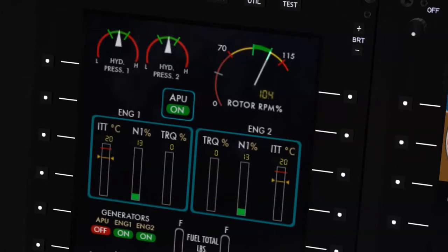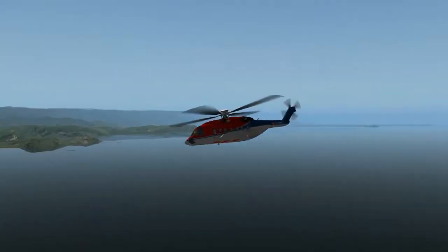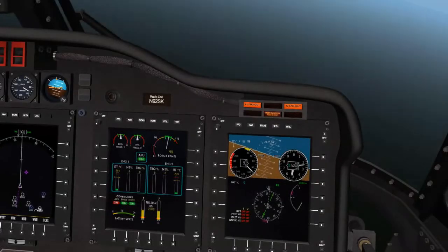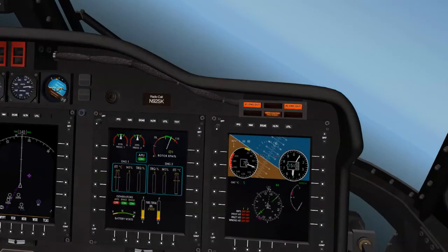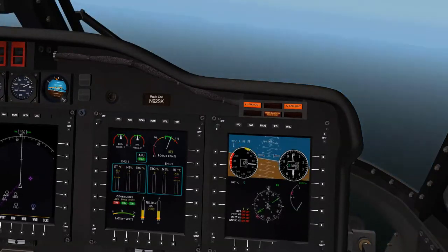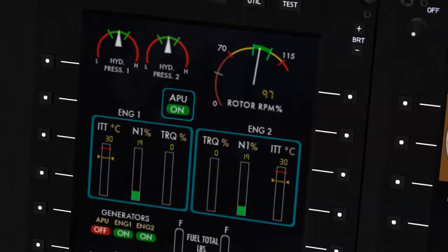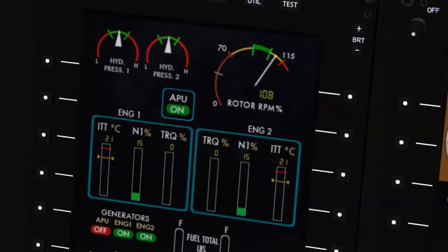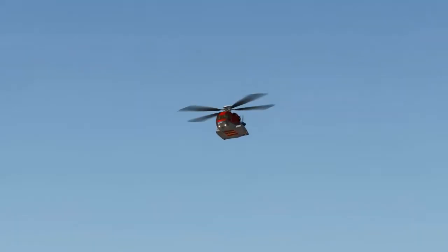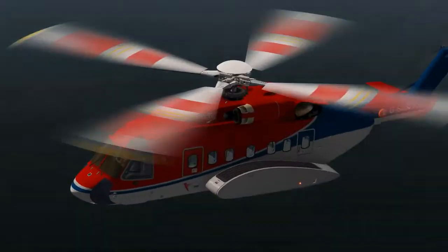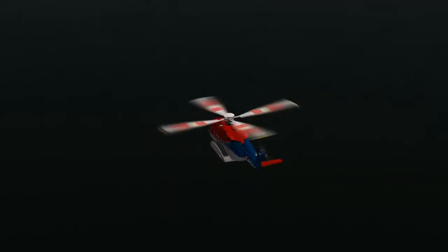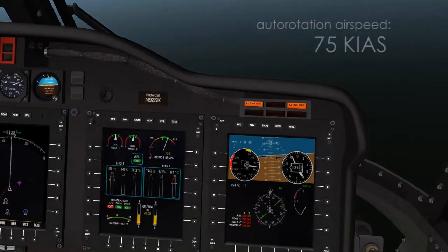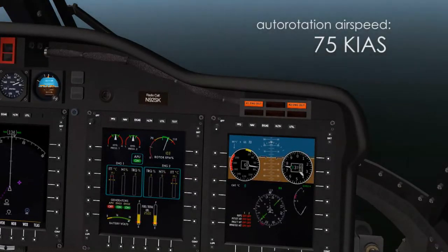Now, just like in a fixed-wing plane, the higher that you are, the more time you'll have. So if you're cruising along at 10,000 feet, you'll be auto-rotating a long time, not necessarily doing anything. I guess you could be trying to restart the engines or troubleshooting whatever the problem is, but as far as the flight control inputs, once you have that set, it's just a matter of keeping the rotor RPMs where they should be and steering where you need to go. And that's basically it for a while. I guess I sort of glossed over the fact that during your auto-rotation, you want to maintain forward airspeed, maybe somewhere between 70 and 80 knots. And that airspeed will come into play in a very important way when we reach the bottom.